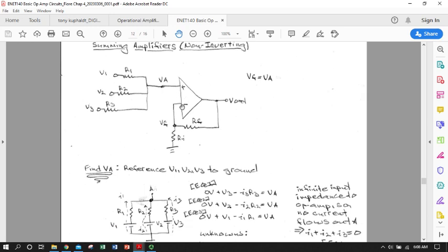Notice in all of these cases we may have a lot of resistor networks on the non-inverting terminal, but our feedback loop, remember, always has to be back to the inverting terminal or it wouldn't be negative feedback. And the last amplifier we'll deal with is what we call a differential amplifier that has summing and some amount of feedback on both, but will have a net negative feedback, and that'll always be through your inverting terminal.